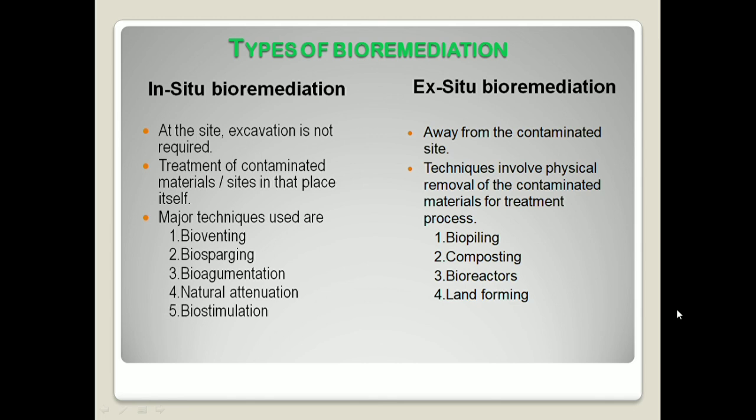Treatment of contaminated materials or contaminated sites is done at the contaminated place itself. The major techniques used under this type are bioventing, biosparging, bioaugmentation, natural attenuation, and biostimulation.